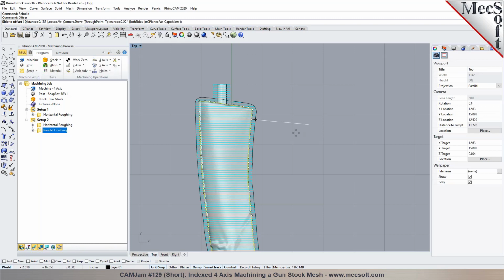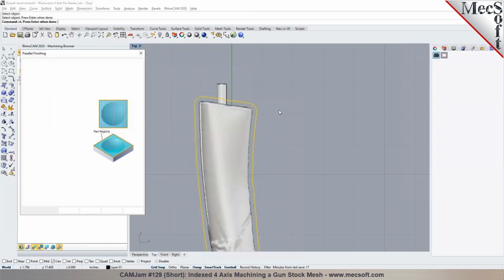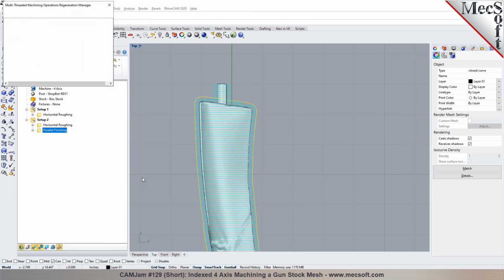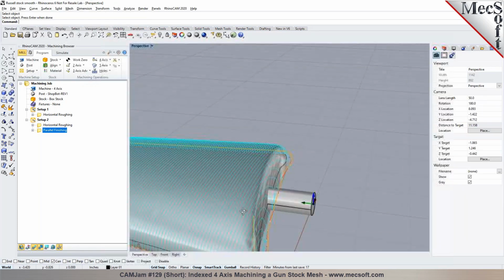And I can specify a region in here. So if you're going to be using a 1/4-inch tool, what I'm going to do is use this as my boundary to contain the toolpath to. So the toolpaths will be automatically contained to this area, as you see it, right?